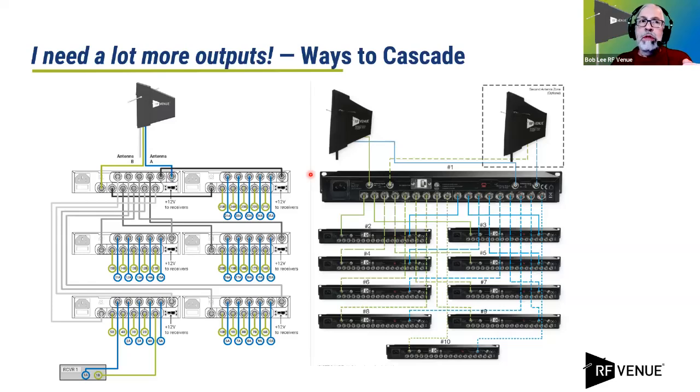easier to troubleshoot. So if you know you have 1A and 1B going to your first receiver, 2A and 2B going to your second receiver, and so on, if you get any trouble, it's going to make it a lot easier to troubleshoot and find out what's going wrong. But there just isn't any functional or any technical reason for doing that. It's just strictly a matter of organizing your system well.